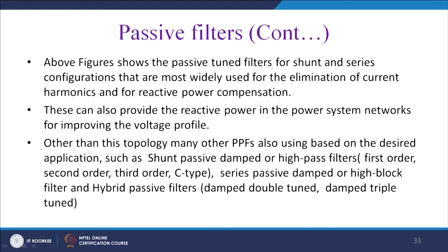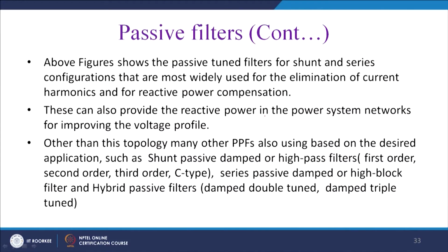So, the above figure shows the passive tuned filters for the shunt and series configurations that are most widely used for the elimination of the current harmonics and for reactive power compensation. So, we can enhance the power factor. In most of the cases we feed this load to feed the drive, and thus we have a negative VAR, and for this reason this filter is required to be capacitive in nature. This can also provide the reactive power in the power system network for improving the voltage profile.